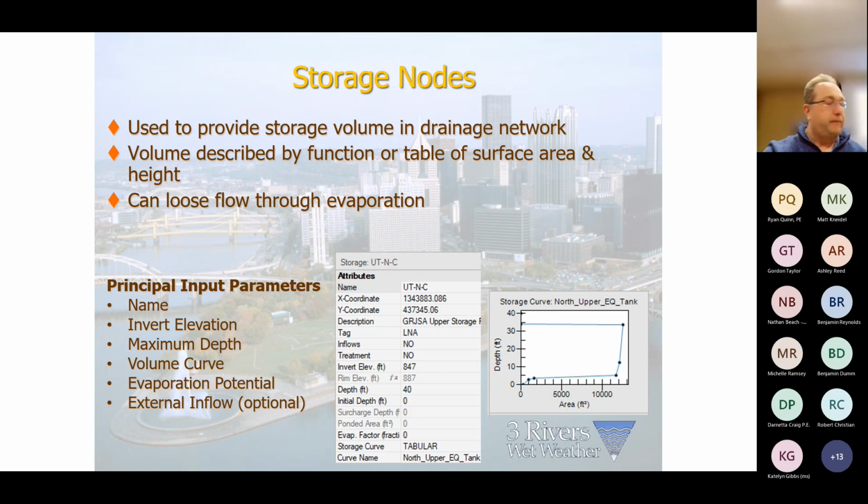And Colin, I'm glad you brought it up. I was always frustrated with the fact that I couldn't put a surcharge depth on a storage. And the fact is if that's locked down, it's not going to flood out of that structure. It's going to push, I guess, flow further upstream. But you're saying that the appropriate way to do that is you're just adjusting that depth. Yes. Okay.